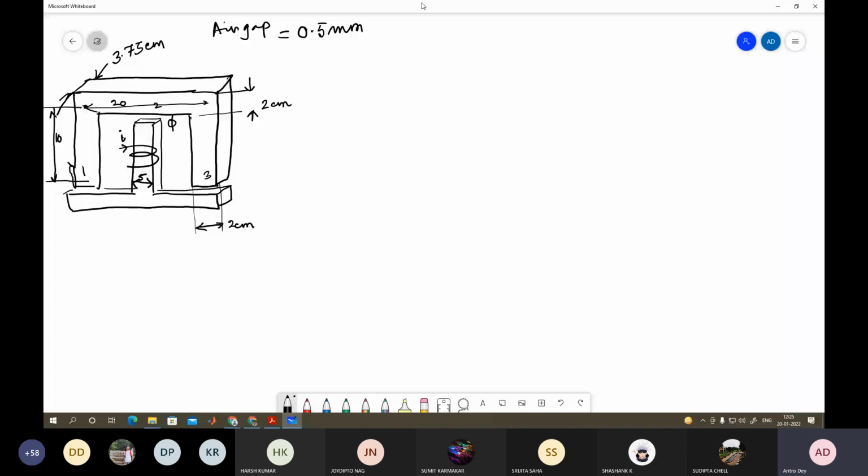Then in that case, how can you solve the problem when you are given a table like this? There is a table which is also given, the H and B table. So H is equal to 440, for that B is equal to 0.8, then 440, 0.9, 500, it is 1. B is in Tesla, and H is in ampere-turns per m. Okay, that is the unit. This is in Tesla. This is ampere-turns per m. So that table you are given. So based on that, you have to solve it.